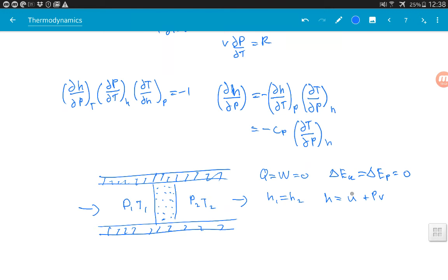But for the ideal condition, although there will be a change of pressure, because the pressure is high here as the gas is flowing from here and then freely expands to a lower pressure P2, the volume here increases, so the internal energy remains unchanged. Pressure P1 is higher than P2 because the gas flows through the plug to create another pressure P2.